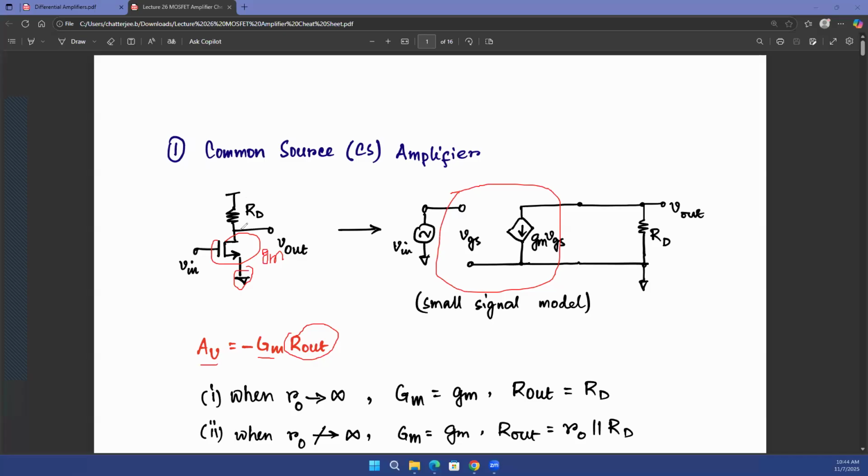And that's why to find out the overall AC resistance, you connect this RD between this Vout node and ground, even though this top terminal is a VDD. When you're doing an AC analysis, VDD also becomes an AC ground. So just again, something that you already know, I wanted to repeat it just so that we know all these important concepts before we start discussing the deeper details.